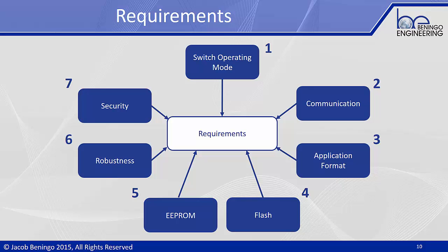We then want to consider the requirements for the flash system. These are going to be simple requirements like the ability to erase certain areas within the flash space. Maybe be able to write different areas, read different areas. Those types of requirements. Those same flash requirements are also going to be required for the most part if you have an onboard EEPROM. If you don't have EEPROM, then the fifth area isn't of any concern. But if you do have it, you need to ask those same questions.